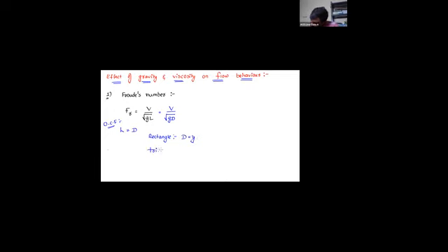In the case of a triangle, D is equal to y by 2. In the case of a trapezoidal, as half of a regular hexagon, D is equal to 3 by 4 y. If you have any doubt, you can go back and look.